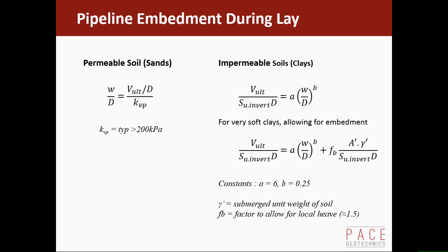So how we actually might calculate the embedment is using these equations here for sands and clays, based on V-ult, which is the touchdown load of the pipeline. So it's not the weight per unit length. V-ult will probably be about twice the weight per unit length. And there's some constants in the equations, a bit of a fudge.